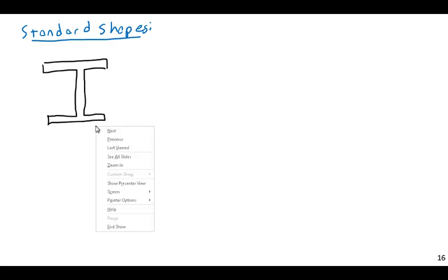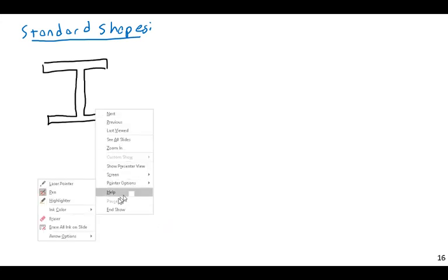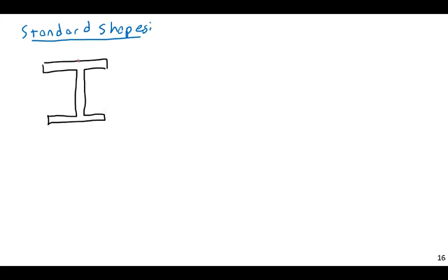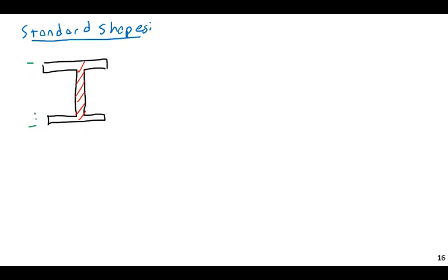So our W section here, let us say it will be mainly carrying shear, it'll be carrying shear really only through its web. So the web really carries all the shear load. The shear is carried through here. These cannot transfer any shear, well, they can try to, but we really treat them as carrying all of their shear through the web. So when we're actually calculating shear in steel design, we neglect the flange entirely. Basically, the web carries the shear and the flanges carry the moment.